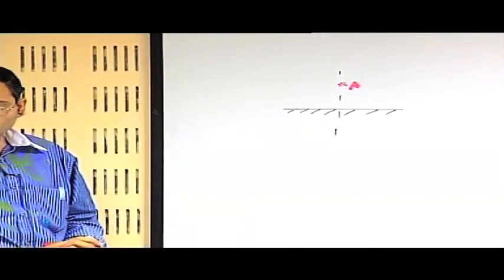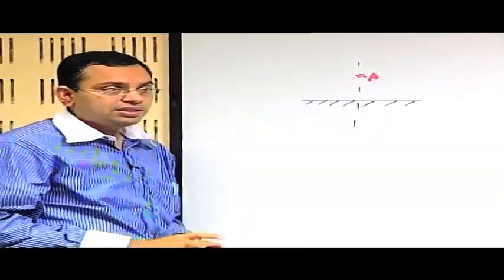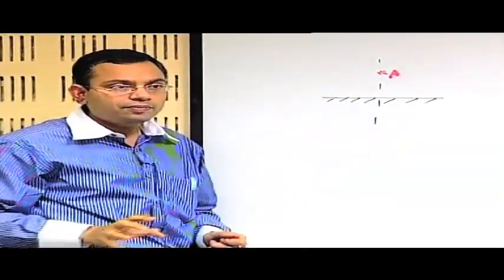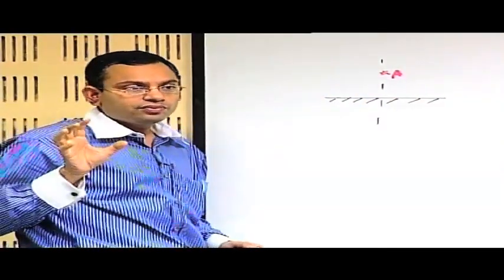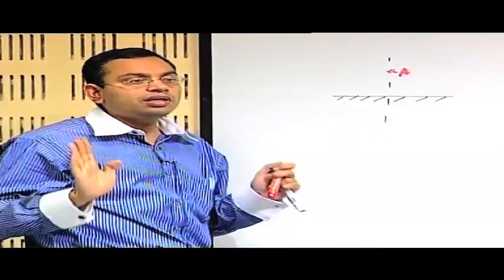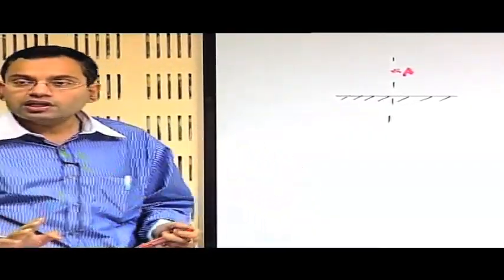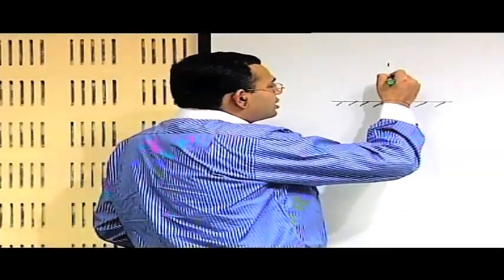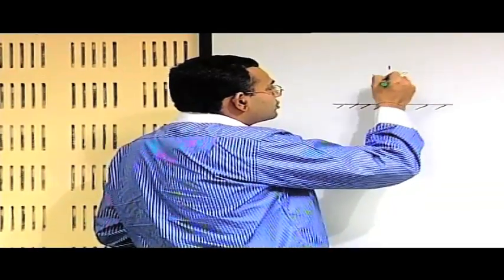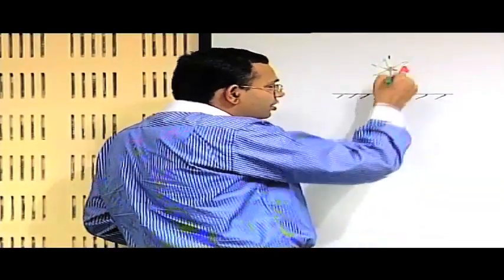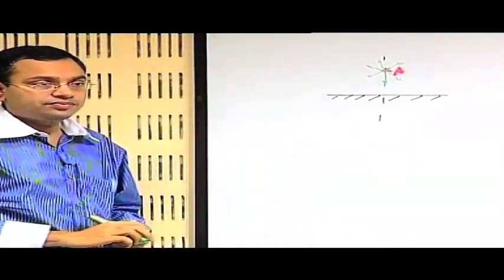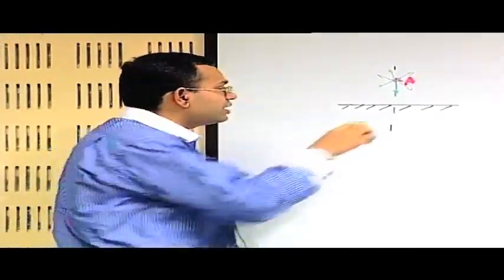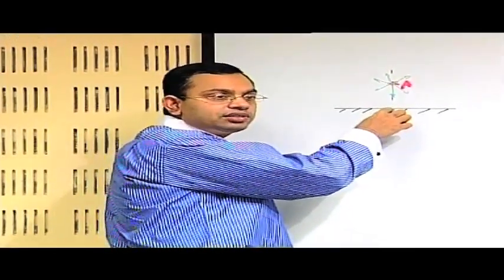So how do we do that? Given this source is already existing, we have to keep one thing in mind. We are talking about a potential flow in this example. When we are talking about a potential flow, it means that the no penetration boundary condition is the only boundary condition that we have to satisfy at the wall. The source radially emits flow in all possible directions, which means it also emits a flow radially in the downward direction. Now, do you have a clue what we should do to make sure that there is zero normal component of velocity at the wall?